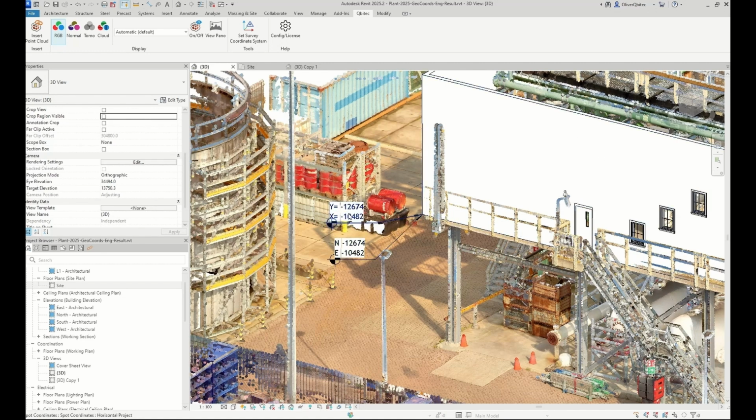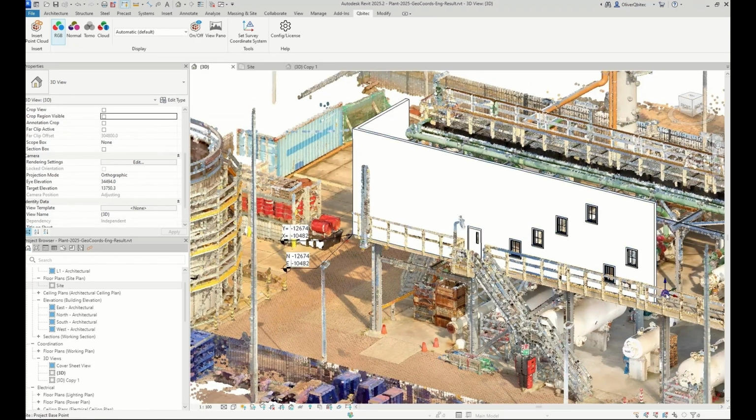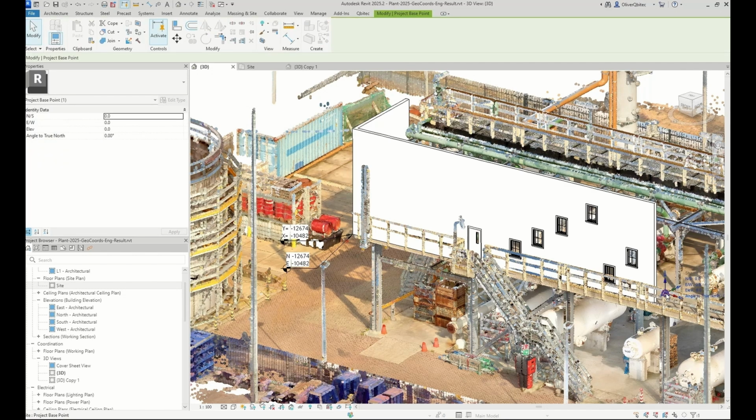These coordinates point to the same wall corner and initially have the same value because the origins of all coordinate systems are in the same place. I'll move them away. Now I have the project coordinate system here. The numbers at the top change. The numbers at the bottom stay the same, or the other way around. Here is the survey coordinate system. If I move it, only the coordinates specified in the survey coordinates will change, whereas the project coordinates remain unchanged because the reference point has not changed.